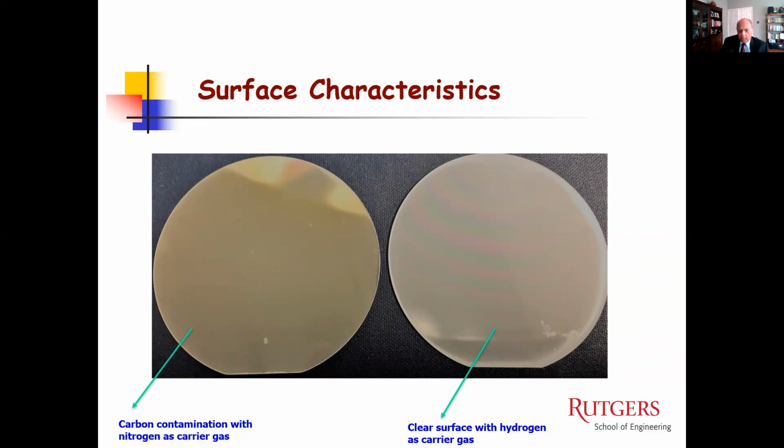The second thing is that most of the things that increase the rate of production or the deposition rate affect the quality adversely. If you increase the gallium concentration, you get more deposition, but the quality of the crystal is worse. You increase the pressure, again, good deposition, but the quality of the crystal is worse. And the same thing happens with the inlet and many other situations. Rotation is very good. Rotation increases the deposition rate a little bit, but makes the quality and uniformity better. So you obviously have an optimal situation.